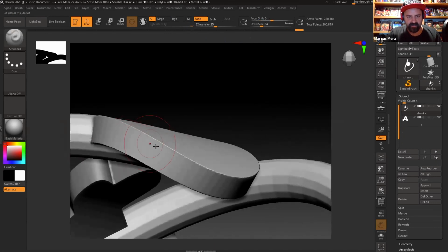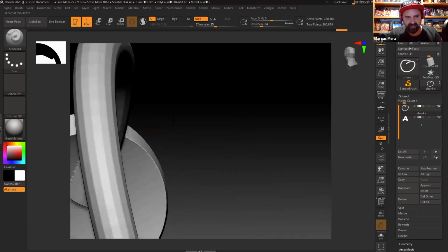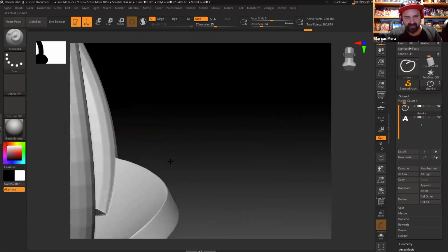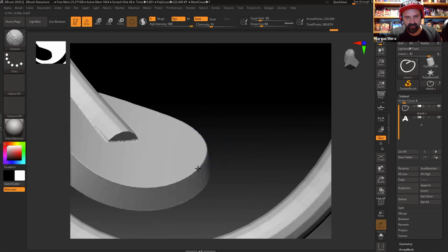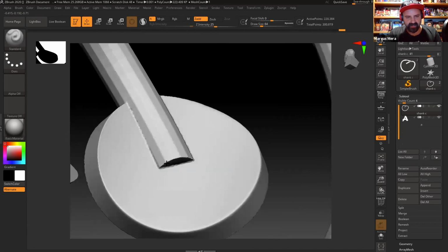All right, especially when you go to the edges here. If I left click and I hit it, it's a little too intense. So let's bring that down a little further. And now when I hit Shift, it's okay, there you go. So it's just taking off a little bit of that bite from the CAD and softening the edge. That's important when you're casting, you don't want super sharp edges because the metal won't flow into that and you'll get investment stuck in there, and that's problematic. You don't want that. So let's get rid of this.